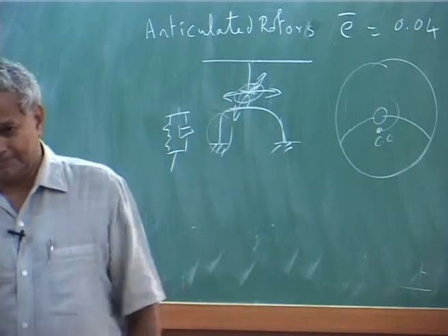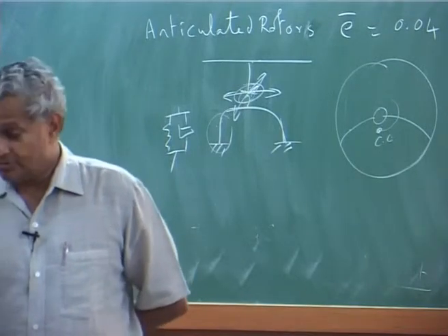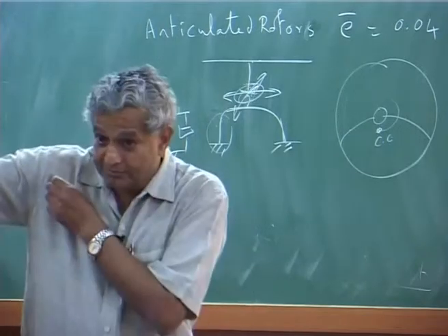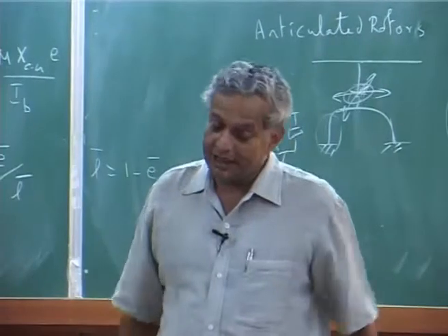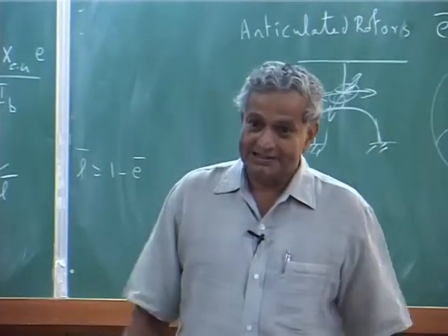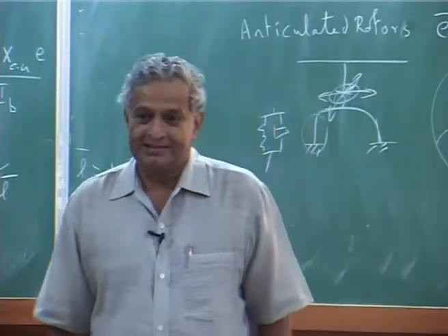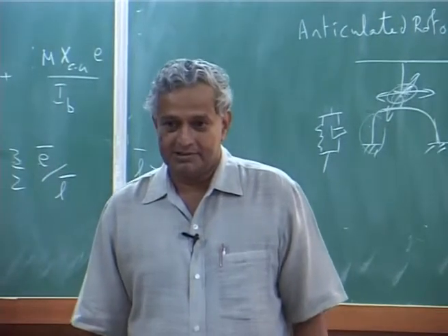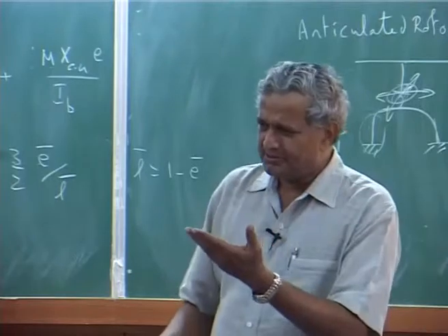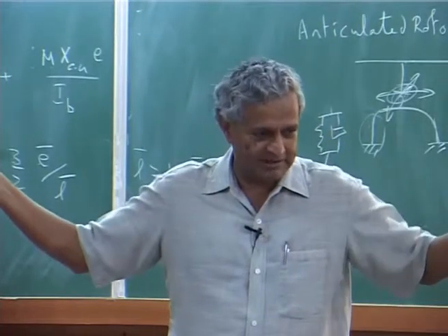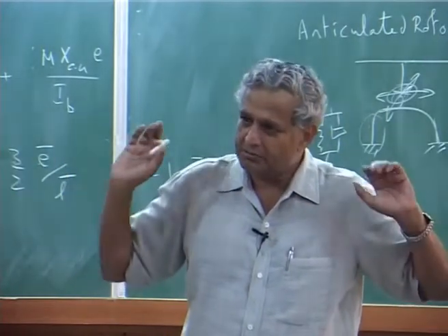You may then put a damper, because your tail boom with the lead lag can get into that instability, like a ground resonance with the support structure. That is what happened in the tilt rotor, what he was showing that day, the amount of problems they see.